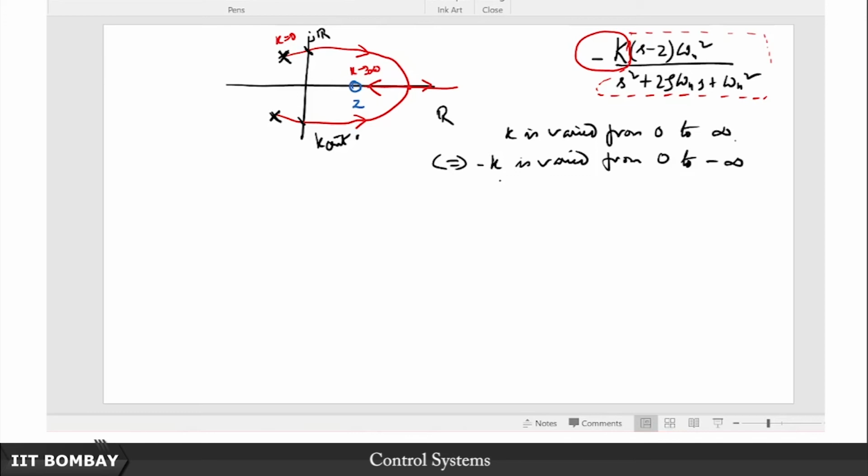After all, integral action means there has to be an addition of an integrator, so it is a dynamic controller. What if I just use very high values of static gain k? It is an easy controller to tune. So I am just going to use a very high value of k. I don't mind very small, negligible steady state error. I am not that finicky about ensuring absolutely perfect 0 steady state error. After all, steady state only happens asymptotically in any case.